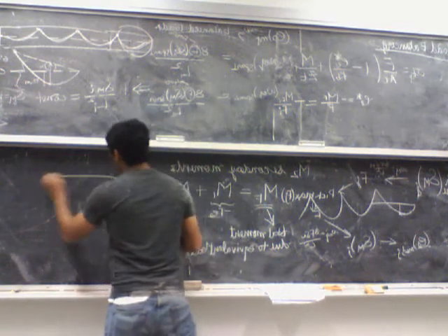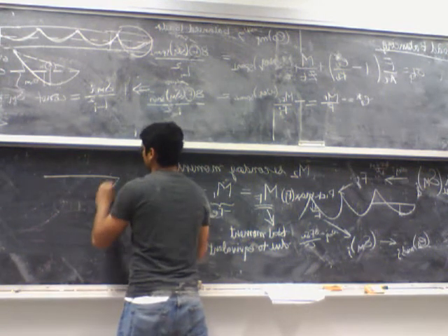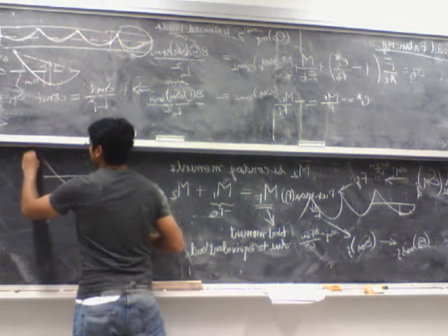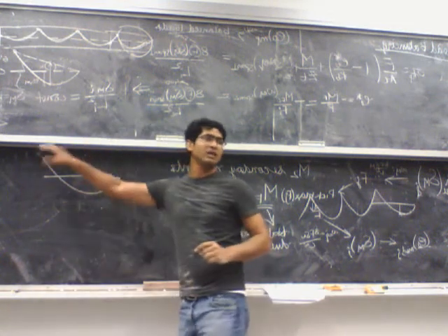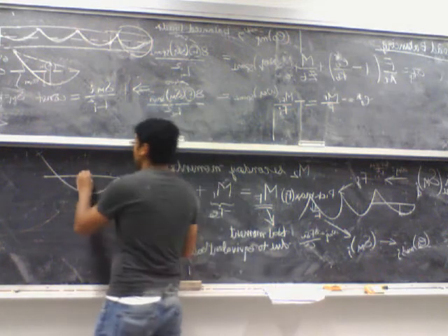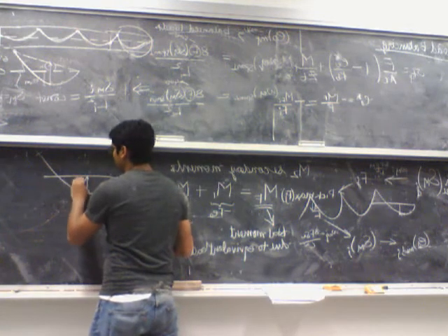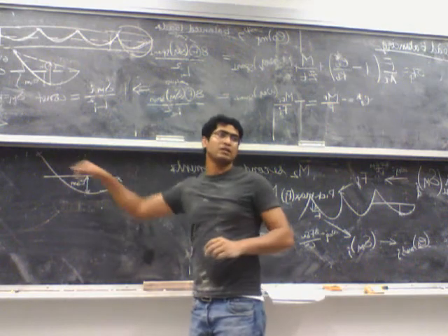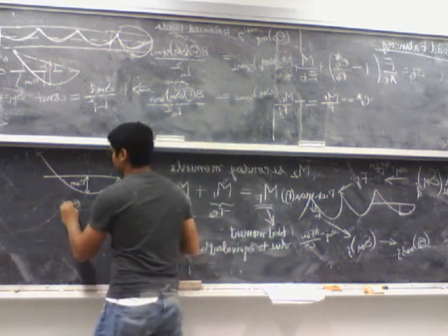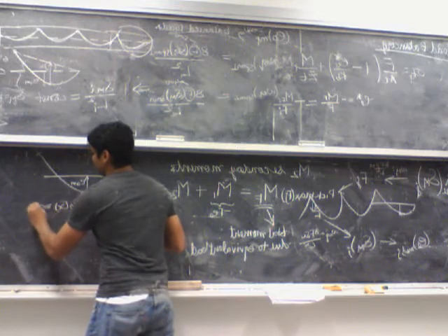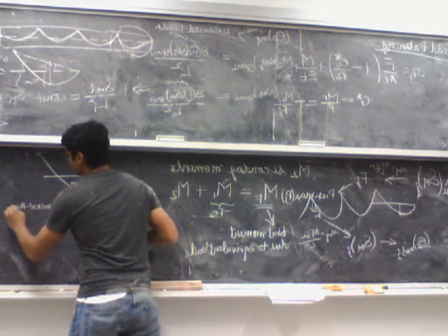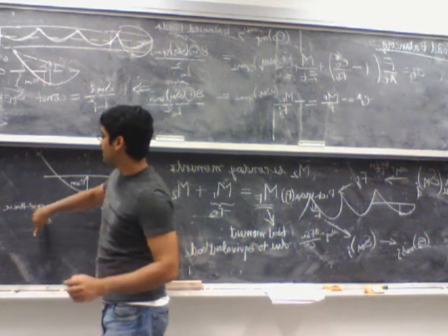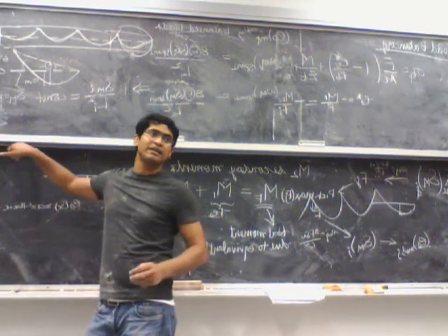So what you'll have is, let's say, you know this value at the end, you already fixed this value, let's say 6 inches or minus 5.17. And what you have calculated is this value, E naught at the midspan, right? So since I know it's a parabolic tendon, it has the equation E naught equals a x squared plus b x plus c, right? So I only need to define a, b and c. I can define the entire tendon.